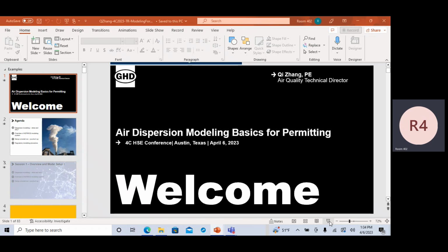So you will be basically adding 20 degrees to the ambient air. AERMOD can take that. Very seldom used. Most commonly used is 0. Sometimes you don't know, or you just know that it is basically ambient temperature, just use 0. I have not used the negative option before.